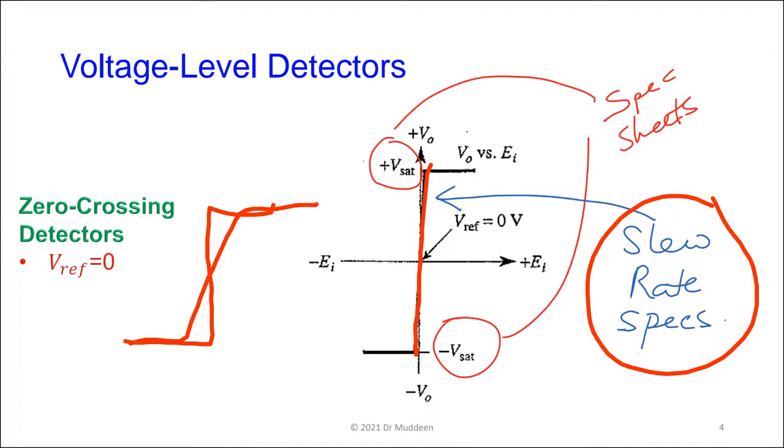And there's also, in between the various junctions and the conductors of the piece of silicon, capacitances as well. There are something called parasitic capacitances, and then there are others that are there intentionally. Capacitors take time to charge and discharge. So in the end, the charging and discharging of capacitors, no matter how small, limits how fast any electronic circuit can move from one voltage level to another.